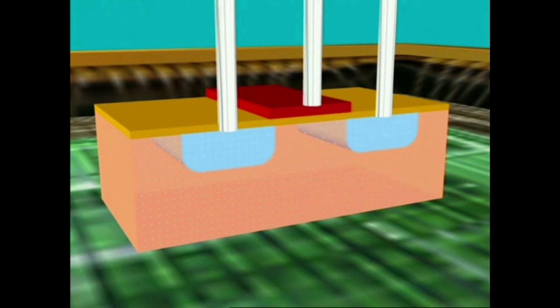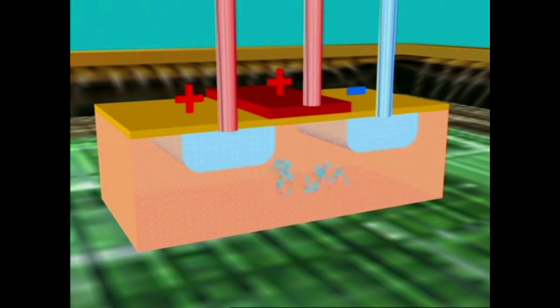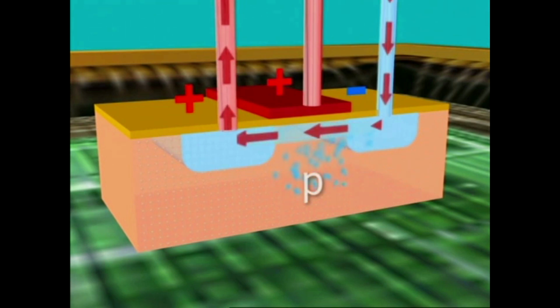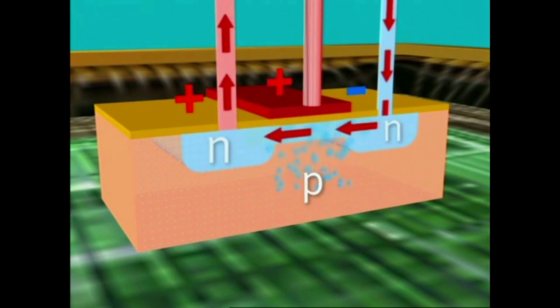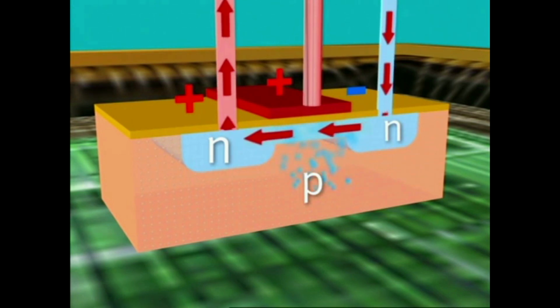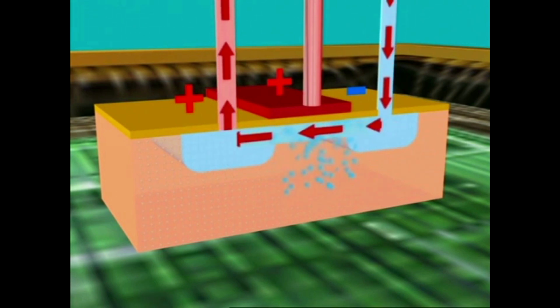If we apply an electrical charge only to the 2 outer connections, electricity is unable to flow and the transistor is blocked. Things are different when an additional charge is applied to the middle connection. The electrons from the P layer are now attracted towards the middle connection and accumulate at the border area between the silicon crystal and the insulating gate oxide. A channel through which the electrons can flow is formed between the islands of N-conductive material. The electrical circuit is closed.